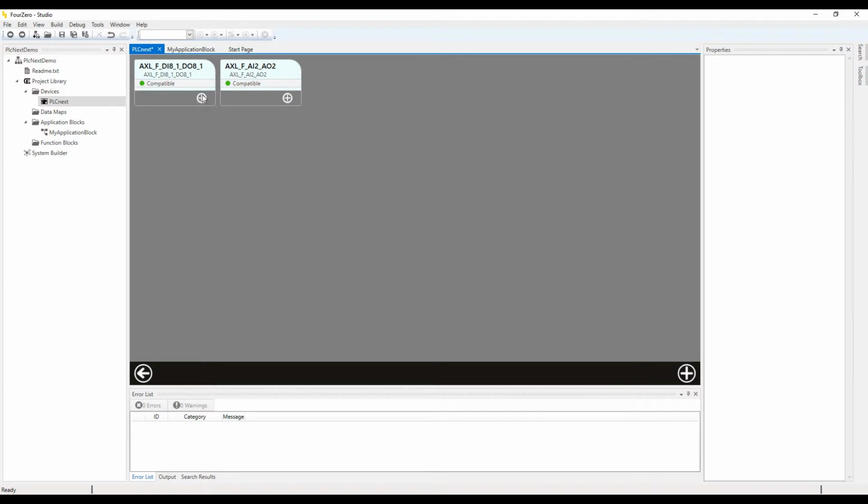So if you use the service providers, make sure that you specify the right consecutive number parameters. In my case, this is the same setting that we have also seen in the first video from the PLCnext Engineer. So you have to specify which position on the Axioline bus your modules are located at. In this case, we still have the PLCnext starter kit, which has the digital I/O module installed in the first place and the analog I/O module installed in the second place.